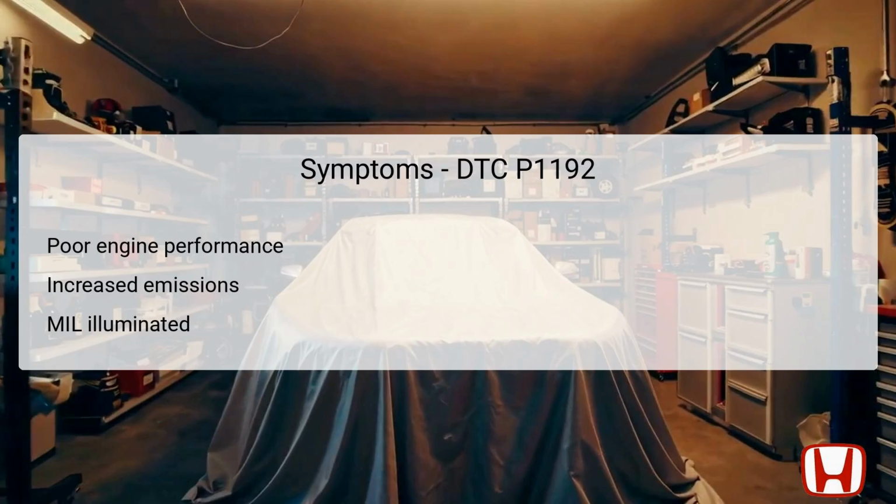When encountering DTC P1192, several symptoms may manifest in the vehicle's performance. One common symptom is poor engine performance, as the low voltage reading from the FTP sensor can affect fuel delivery, leading to sluggish acceleration and decreased power.